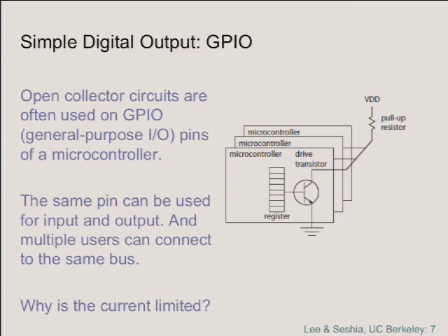Mostly you're not going to have to worry too much about bus protocols in the lab, because they tend to be internal to these devices. And the way that you interface with these devices is through this concept of memory mapped registers. And as soon as you understand how memory mapped registers basically work, you don't have to worry too much about the bus protocols. If you get really fancy, for example, if in your project you're going to be doing FPGA designs where you're putting custom hardware and having it interact with the MicroBlaze, then you probably will need to understand bus protocols. Okay.